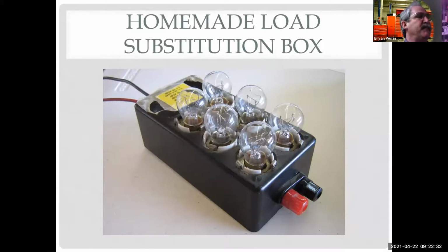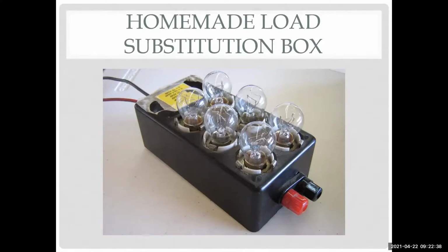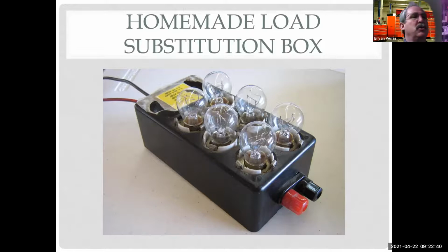If all 6 light bulbs light up nice and bright, that's 15 amps. That means my wiring, connectors, everything else are doing good. So I use this also. If I want to test the power going to a module, I'll unplug the module before I replace the module, make sure I have good power and grounds.